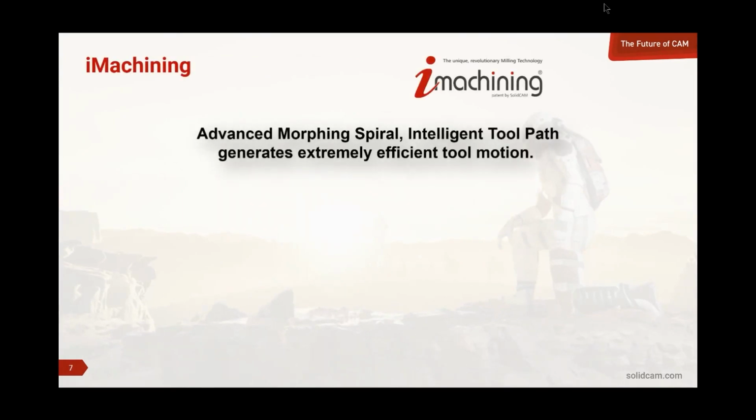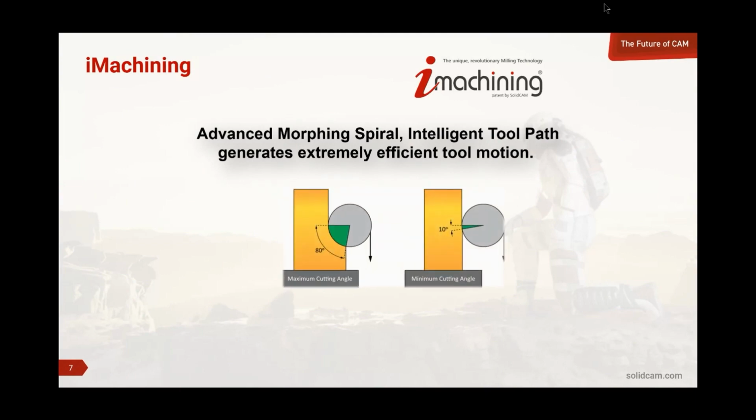We operate with what we call an advanced morphing spiral. It is actually a very intelligent toolpath, and it allows us to range between 10 degrees and 80 degrees in order to manage morphing from one shape to another shape while keeping the tool in contact and giving us a more effective toolpath that is continuously removing chips as much as possible. Okay.